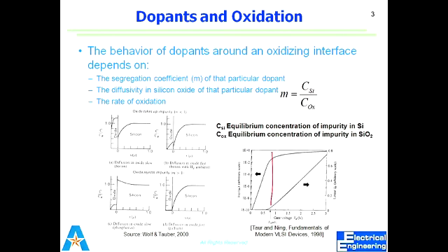If you are still confused, let's suppose I have silicon that is 1 micrometer cube. It's too much actually, that volume is too much. I should say it's 1 nanometer cube. And as I told you, when this silicon is consumed, how much silicon dioxide should be produced? 2 times, 2 nanometer cubes. So when this silicon is consumed, this silicon dioxide is produced.